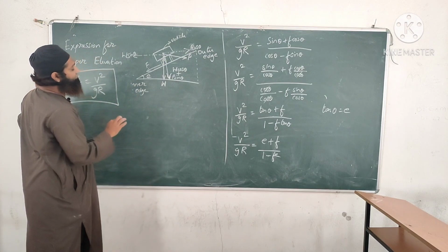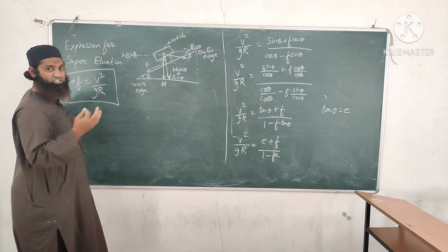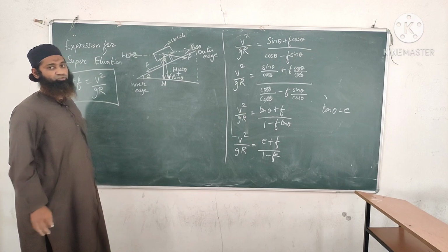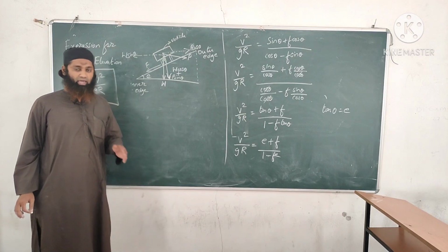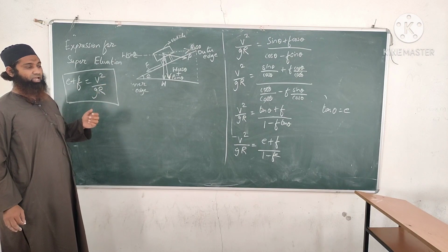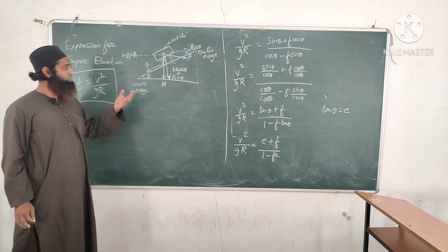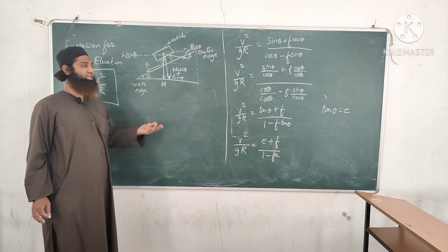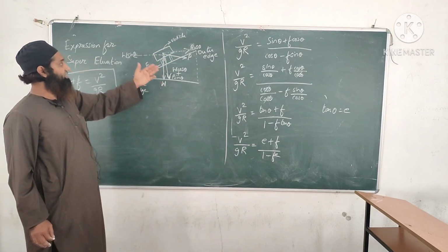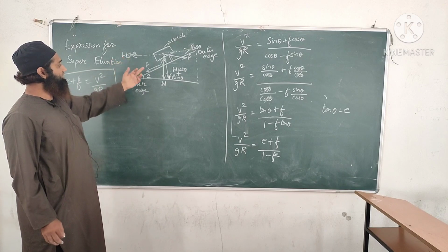Okay, now after that, I have just resolved these forces. Equations of equilibrium, you know, that is sigma x is equal to 0, sigma y is equal to 0, and sigma m is equal to 0. I had taken sigma x is equal to 0, and I have computed all the forces that are acting in the x direction. So in the x direction I have P cos theta, that is acting at the right. On the left side I have W sin theta and the frictional force.